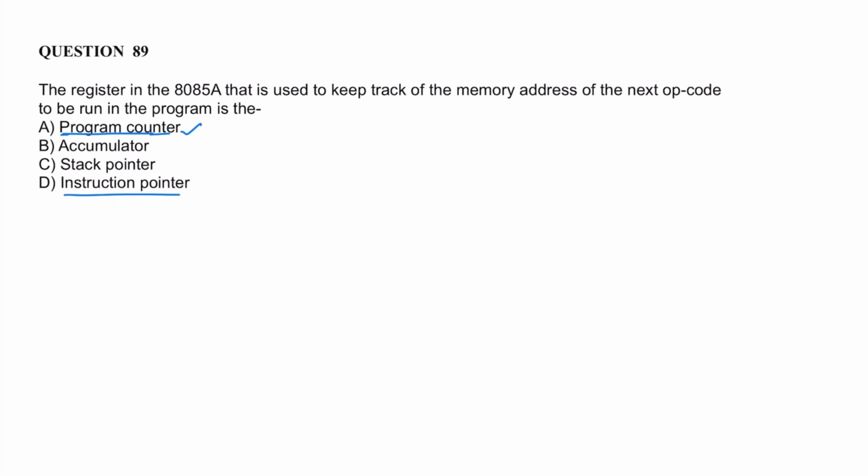The program counter stores the address of the next instruction that is to be executed. The stack pointer register is used to indicate the location of the last item put onto the stack. The stack pointer is a CPU register that holds the memory address of the top of the stack, the address of the top item placed on the stack. It is a last in, first out data structure used for storing data like local variables and function parameters.